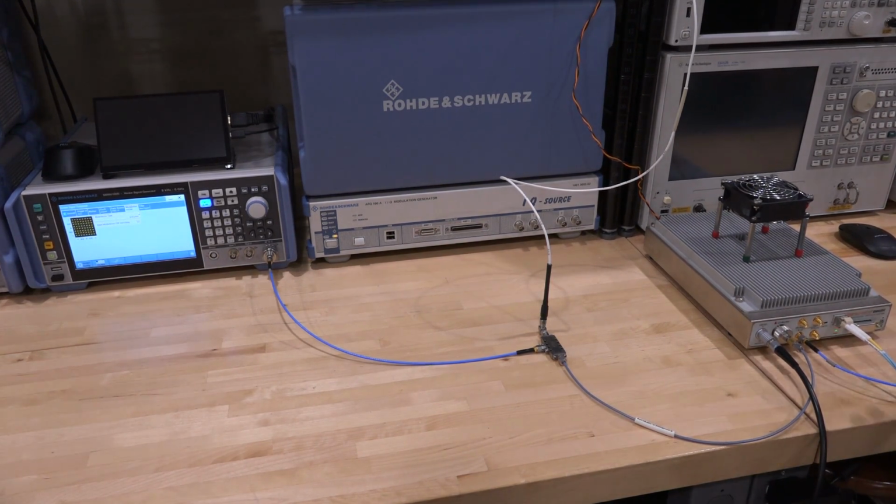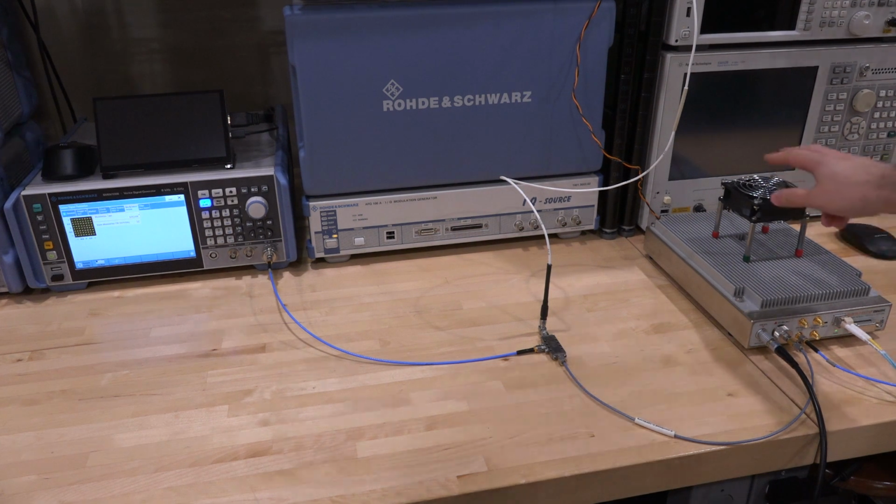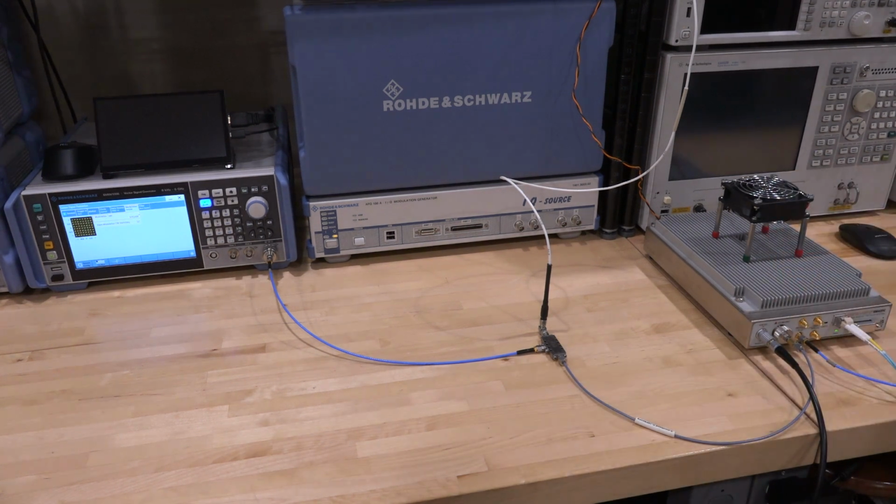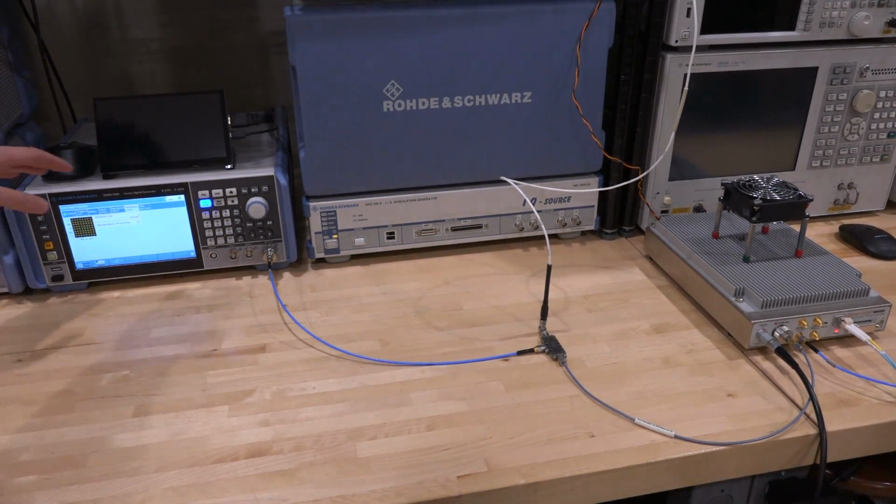And here of course we have our SM435C from Signal-Hound, and I also put a little fan on top of it. This thing does get pretty warm, about 50-55 degrees Celsius, so this is going to help run it a little bit cooler. So in this setup we have our modulation coming in at 100 megasymbols per second. So it's going to occupy just over 100 megahertz of bandwidth. In that situation, we are within the bandwidth of our analyzer, so we should be able to use the built-in functions to look at the modulation and constellation performance.